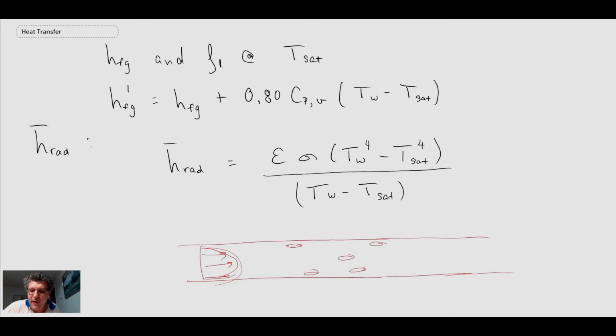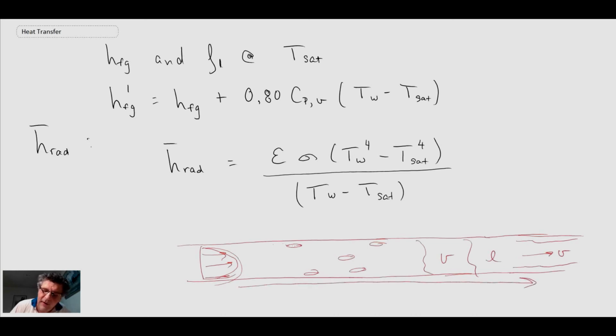and so we can have bubbles, dispersed phase bubbles. We can then go into slug flow, plug flow, where you might have vapor here and then a liquid, and then you can eventually get to a point where you have a core annular flow, where you might have a liquid on the wall and just a vapor in the middle. And then you can get to a point where you get a mist flow, and then you have entirely vapor. So it's a very complex process going through the transition for multi-phase flow, and consequently we're not going to look at it in this course.